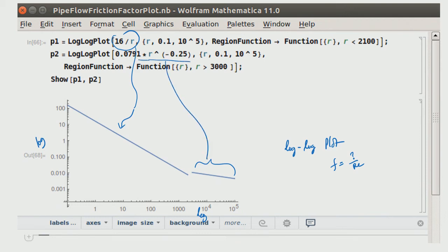So, you could see that on the left hand side of the log plot of friction factor as a function of Reynolds number, you would have basically a straight line for the laminar or analytically derived friction factor, and you would have a fairly flat region. So, you could actually see that straight line drooping downwards and a fairly flat region for laminar and turbulent regimes respectively. So, we will see whether this kind of a trend is replicated in other kinds of domains, and that would be something as a learning as we go along.